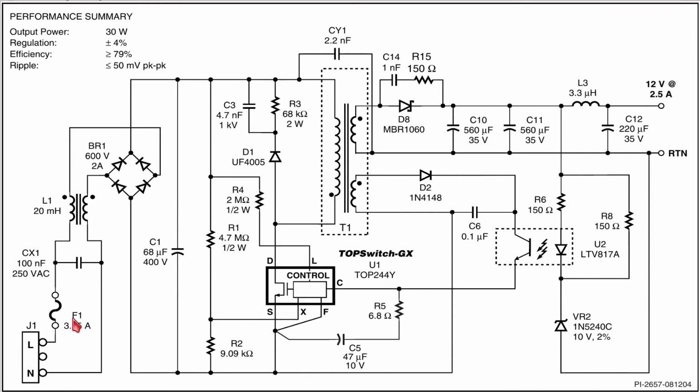So here is the line voltage coming in as AC, there is a fuse, some minimal filtering going on here, then we have the Graetz rectifier bridge which goes into the bulk filtering capacitor. Then we have this resistor network for the over and under voltage protection here. Then we have the integrated circuit, of course, and this is a typical flyback configuration.